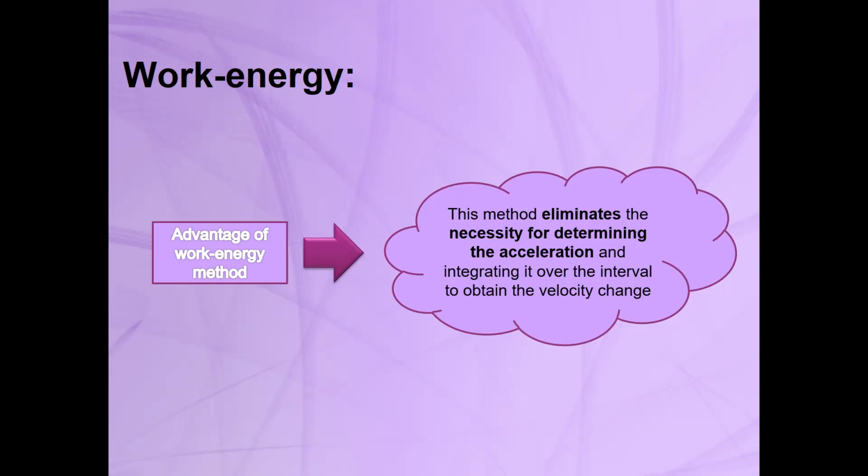But if you use work and energy methods, you don't need to obtain the acceleration. When I say acceleration, I mean both the linear and the angular acceleration. We don't need the kinematics relations for the acceleration. You can easily find the reaction force by using these equations, work and energy.